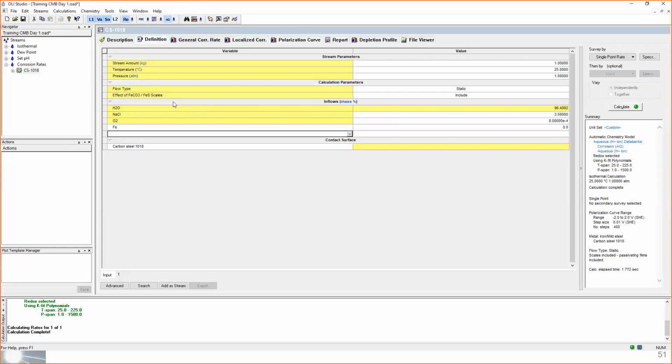We go back to the definition, and I see some questions that I'm going to try to answer. Okay, let me see. So the first question is, I am testing here the same options for this corrosion rate calculation, but my calculate button is yellow instead of green. For carbon steel, well, first let's make sure that we have version 10. In some versions of the software that are not version 10, we haven't calibrated some of the parameters for the corrosion rate.